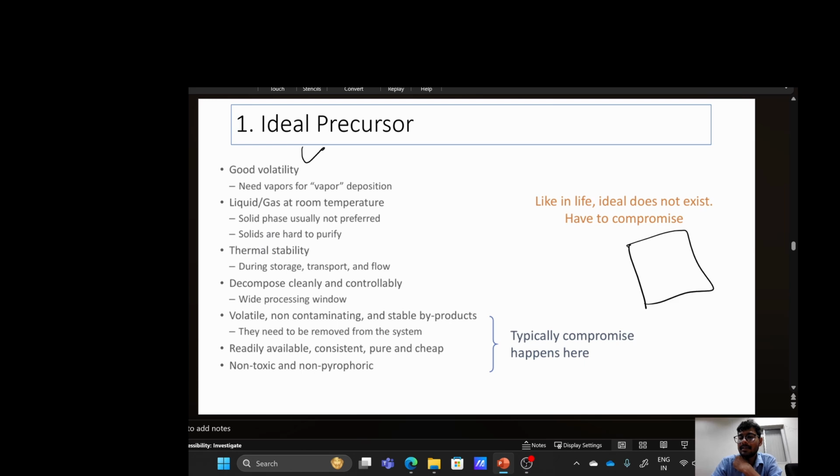If there is a precursor over here, and if we flow nitrogen through this one, and there is a whole next line, the nitrogen will be bubbled through the precursor, and it will get out through this opening to the chamber, which will carry the precursor molecules along with it, and there will be growth. The growth will happen over there.